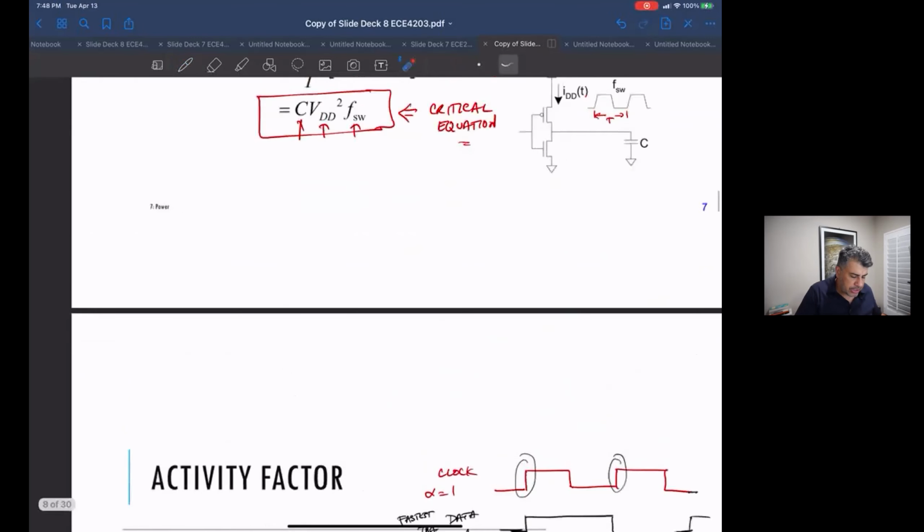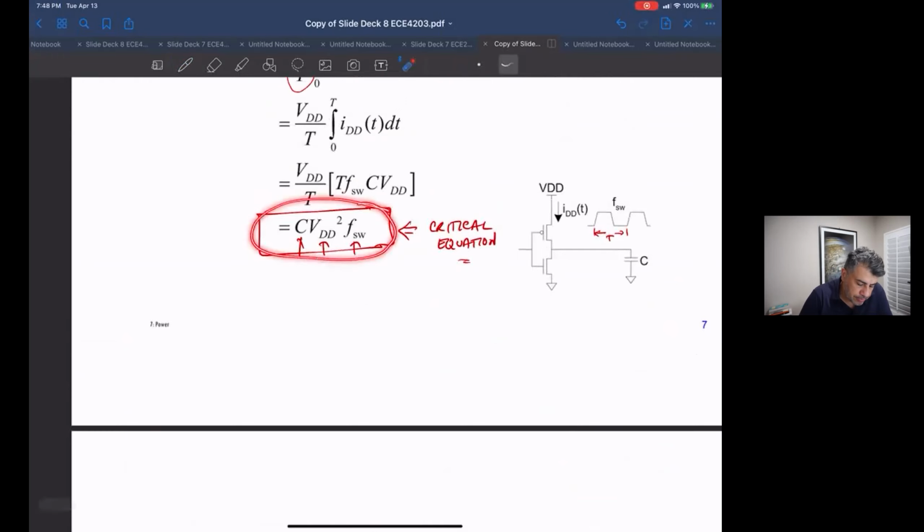By the way, a couple of important things here. So back to this equation for a second. Notice that the power consumption is linearly dependent on the capacitance and the operating frequency, but it's square law dependent on the supply. So if you somehow manage to get absolutely the same circuit in a 180 nanometer process, for the sake of discussion, say same C and same switching frequency.